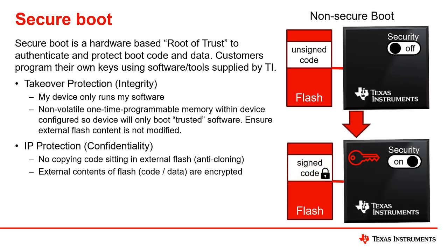For Secure Boot, we're going to pair a key that's going to be stored inside the device with a lock, if you will, with signed code. So we're going to use asymmetric encryption to pair the code that's going to run with the key that's stored in the device, so that when the device boots, if the key doesn't unlock the code, or if it can't handle the signing process, then the device won't boot, thus implementing Secure Boot. And this allows you to start executing security code and really establish your root of trust and maintain a chain of trust all the way up through the upper layers of software that the system is going to run. Really the foundation for security in a modern day embedded system.